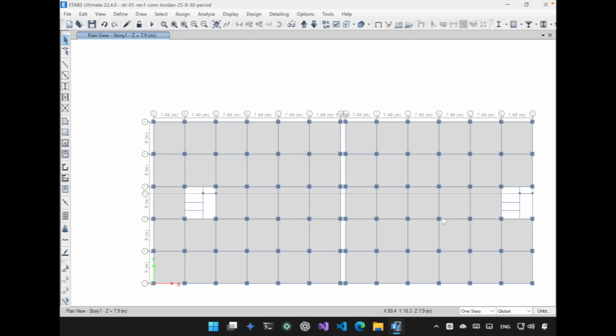calculated seismic loads. The software can compute earthquake forces in two ways, either by using the predefined design code within the software, where we can modify the parameters based on our project, and ETABS will automatically calculate the lateral forces, or by using the user coefficient method, meaning we manually input the earthquake coefficients and the software distributes the lateral forces among the building stories accordingly.